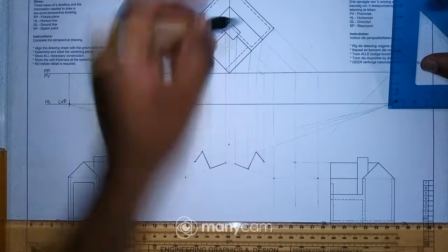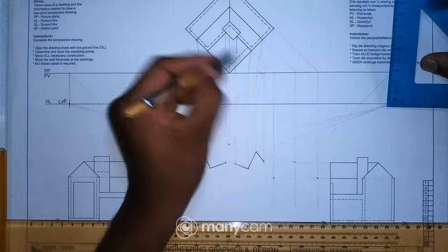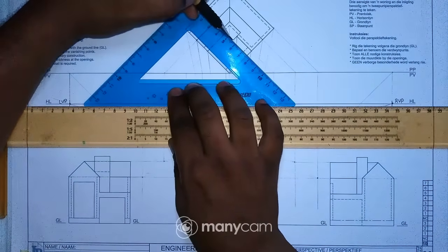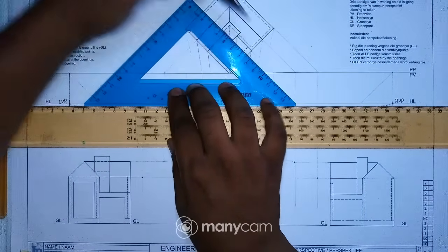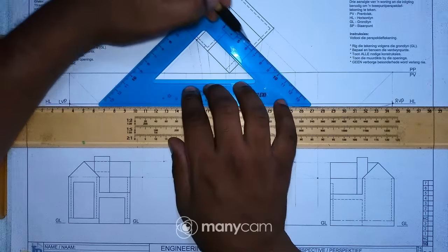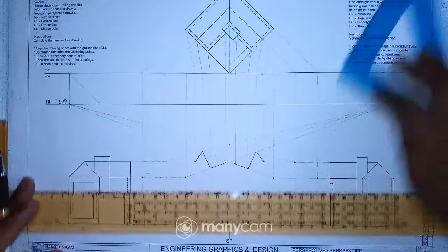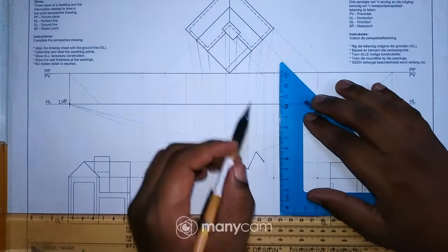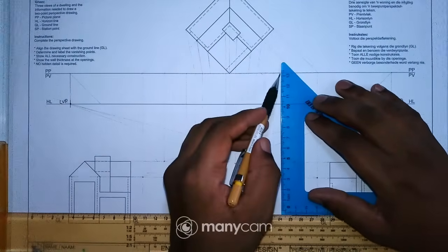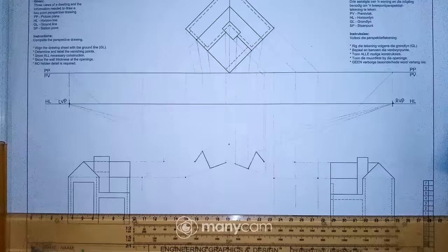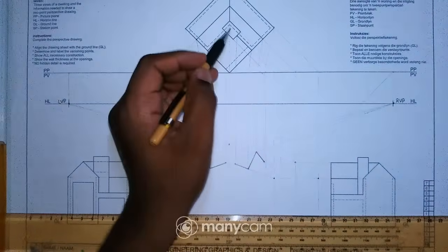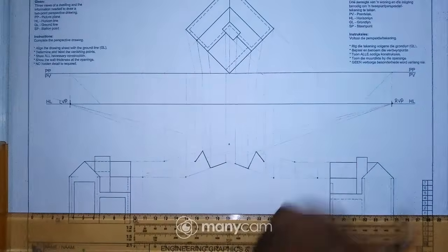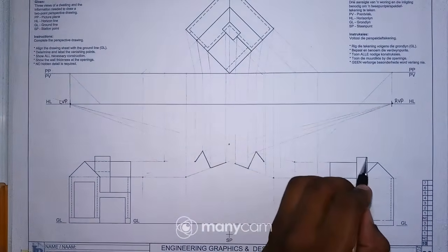So I'll just project these 2 points down in this direction. So just extend this point or line down there, extended line down to the picture plane, and then from there I just draw vertical lines. Where is the other one? It's right there, a vertical line down. Okay, so now I'll start with the top rectangle there. Where is it from my elevation? It's right there, right?